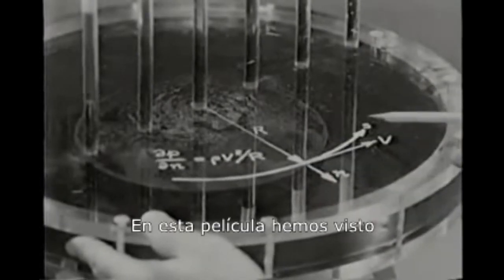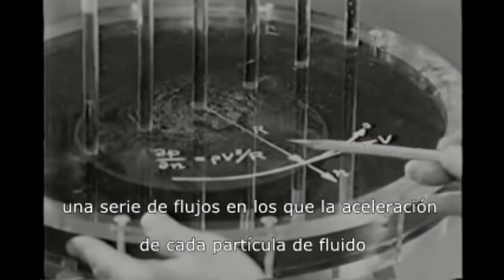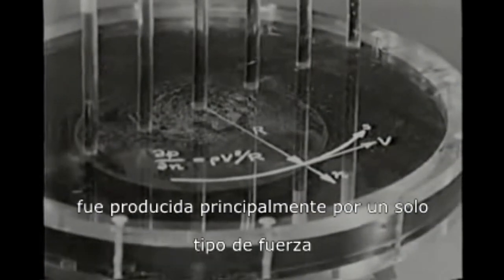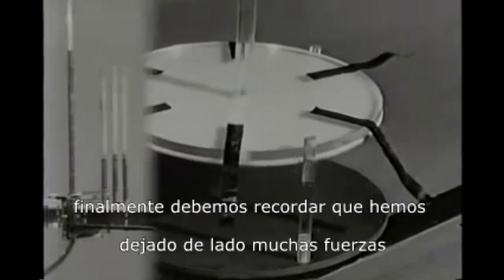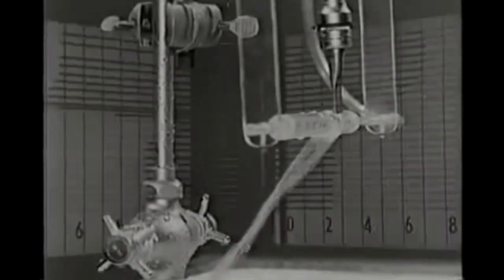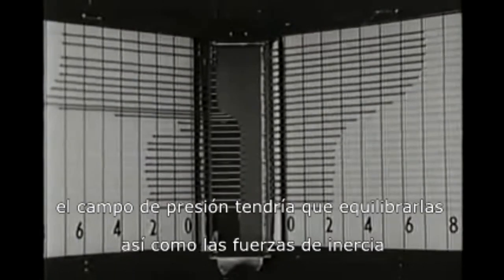We have seen in this film a number of flows where the acceleration of each fluid particle was mainly produced by a single kind of force, the gradient of the pressure field. Finally, we must remember that we have left out many forces: gravity, electromagnetic, and so on. If these were present, the pressure field would have to balance them, as well as the inertial forces.